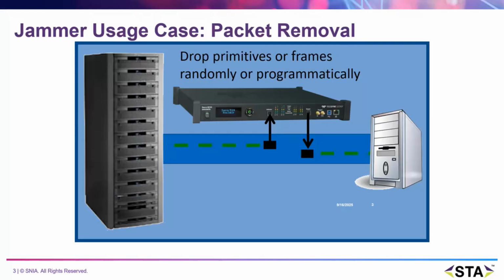SAS primitives are low-level control signals used to manage link-level communication. Examples include ALIGN, IDLE, transmit or receiver ready, synchronization primitives, and BREAK and CONTINUE.